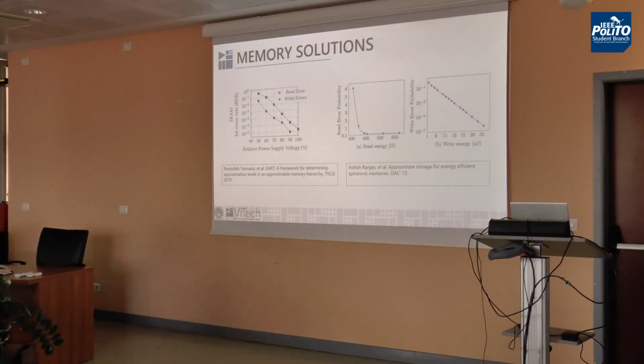And those plots are just the motivation. That one is SRAM, and these ones are STT RAMs. Those plots are just showing that you can reduce, let's say, the voltage of your memories if you are willing to have some mistakes here and there. And again, reducing VDD is really powerful too. I mean, it's always squared, right? If you remember, you double VDD, you are increasing by 4 your consumption. So it's a powerful tool if you can use that.